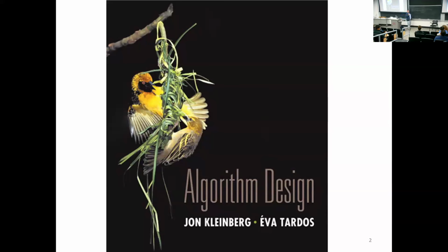If I'm a roboticist and I have all the tools of Gazebo and Bullet and whatever other modeling frameworks, and I had to decide what the state is of this nest being manipulated by this algorithm, I would have a really hard time writing that down concisely. These grasses have directional friction, they have little hairs, and that is really important for holding things together. They're hollow, and when you bend one, there's a little pre-kinked joint, with stiff pieces of grass or little sticks in between. It's totally unclear if this is important to model. And if I try to model it all, it becomes super intractable to reason about the success or failure of a particular weaving algorithm.